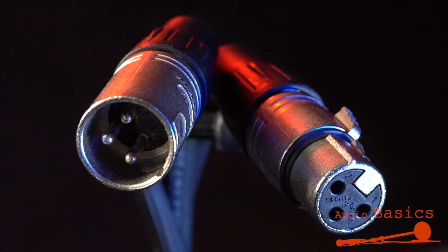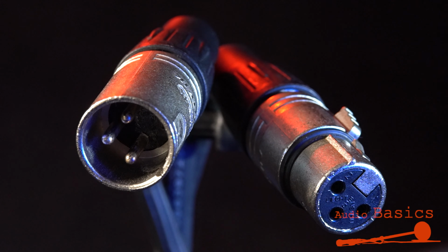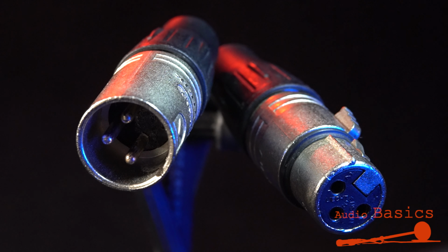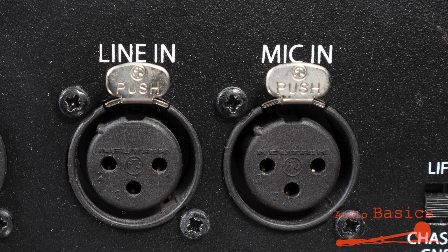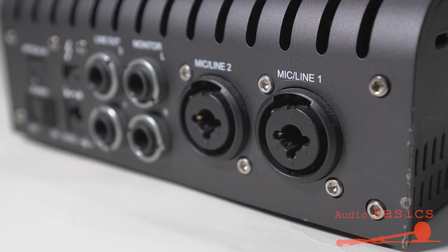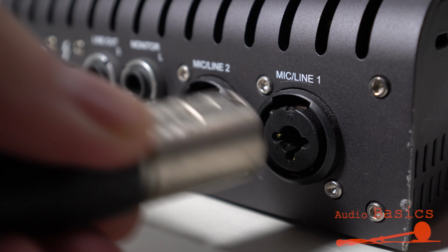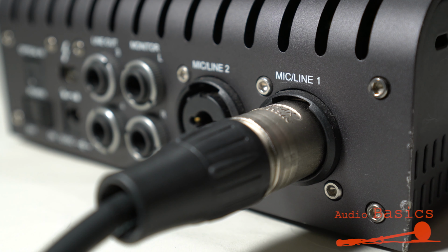After we've got the mic set up on the stand, let's look at connecting it to your interface. A standard XLR cable is your typical connection from mic to its destination. The two ends are opposite each other, so it's easy to figure out which way it's supposed to plug in. The ports on your interface will look either like this or like this. Both allow for an XLR cable to connect, but this one I refer to as a combo jack. It allows you to plug in both XLR and quarter-inch connections from sources such as guitar, keyboards, or external processors.